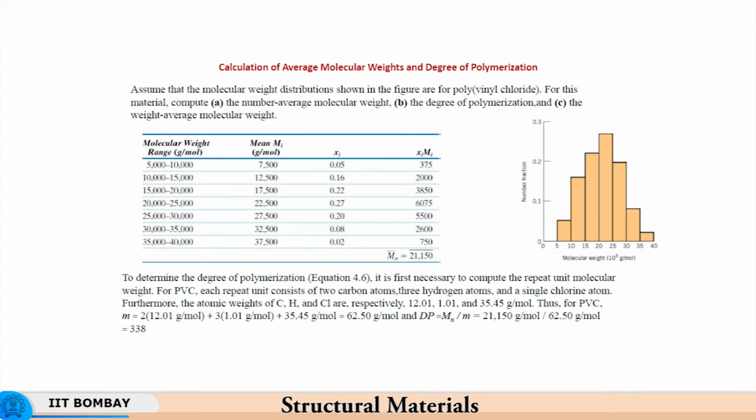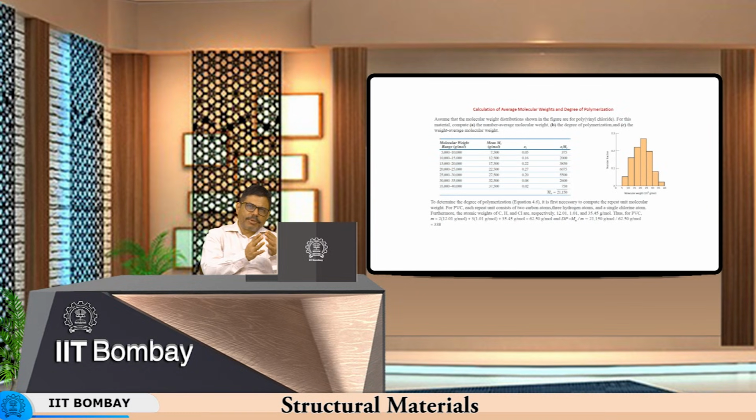Now there is a catch over here. The catch is that because of the chemical nature, when you do repeated recycling, that is repeated heating and processing of the material, the amount of time the material stays at a particular temperature decides the rate of degradation of that polymer. What it means is that if you have a macromolecule which has, let's say, 338 repetitions of the monomer, and you have repeatedly heated and reused the same polymer several times, it is not going to have a macromolecule with the same 338 repetitions.